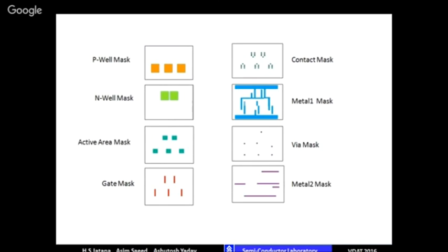In this side the boron will be implanted, and that area will become P. Within that area, if this is P, I will make N transistors here. So this whole thing is P, and the rest of the area, which is white in color, is unchanged.